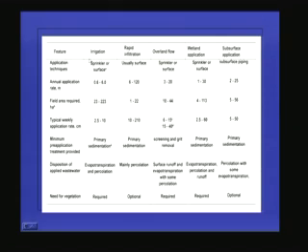If you want to go for irrigation, we can apply using sprinklers or surface irrigation, and for rapid infiltration usually surface application is used. For overland flow, usually sprinklers or surface application can be used, and another treatment method is wetland application. Here also sprinklers or surface application can be used, and for subsurface application, subsurface piping is used. So, these are the different methods used for water treatment using land, and nowadays the wetland application and subsurface applications are gaining more and more attention.